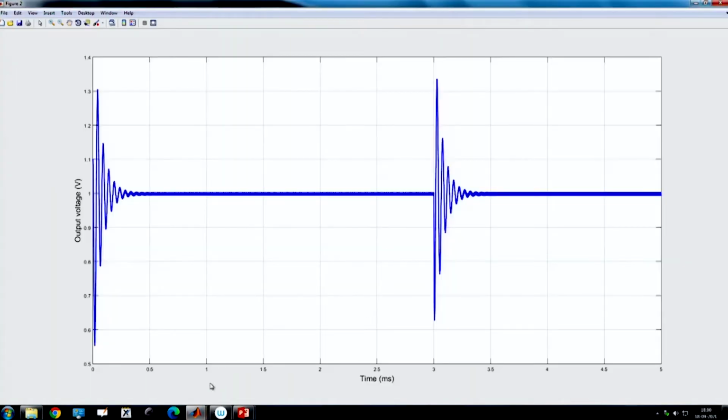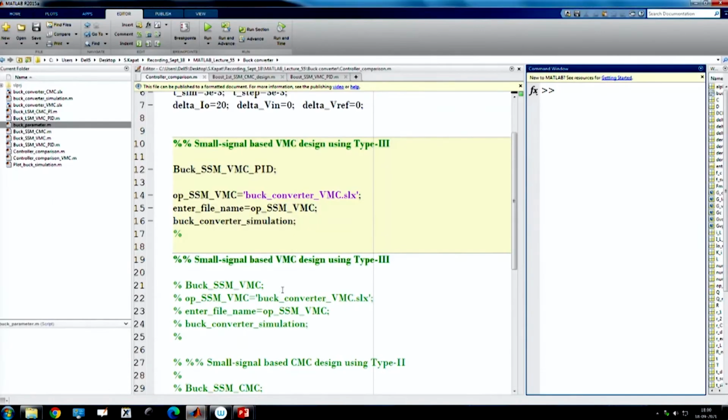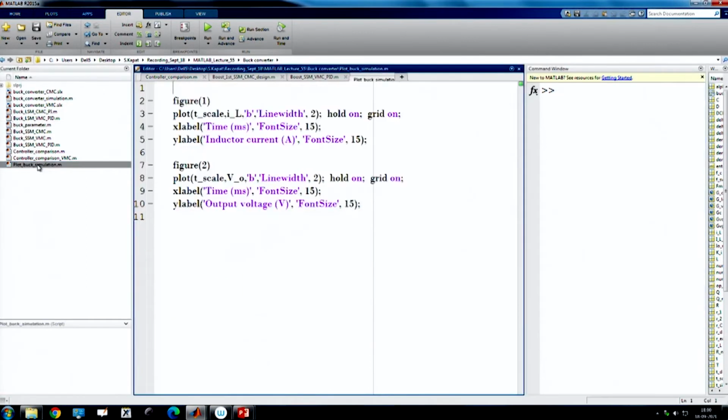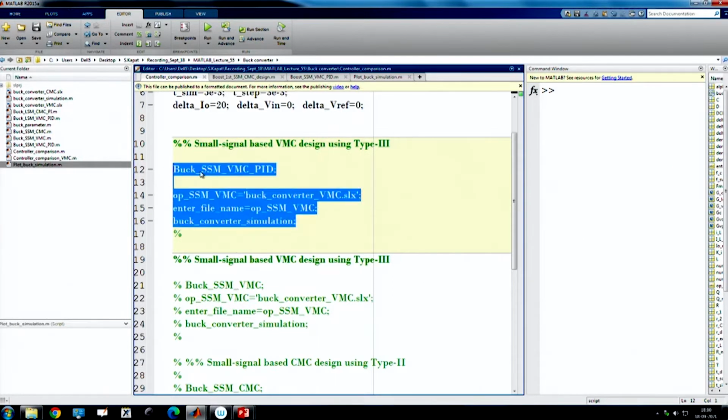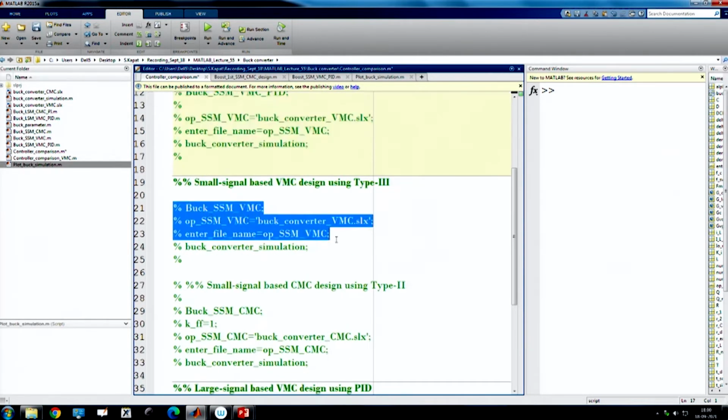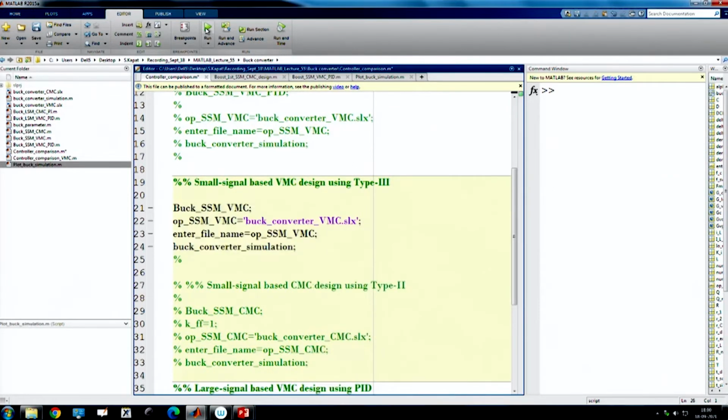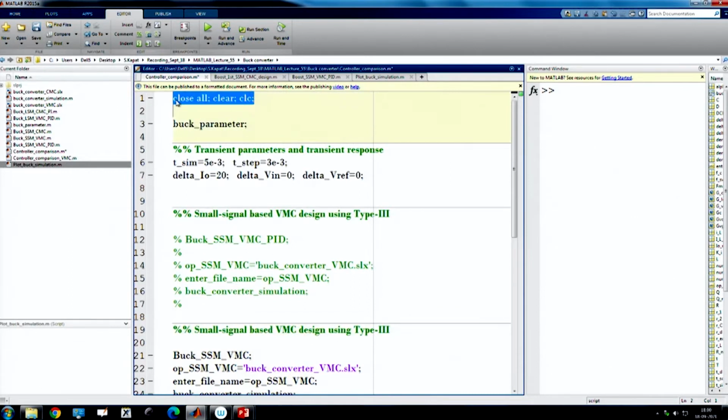We will hold the result, this is using the PID controller in the small signal model. Now, on top of this, let us say we use a red color, we are going for a type 3 compensator. We have already run it commented; this is our type 3 compensator. So, uncomment, now we are running. You need to hold this.